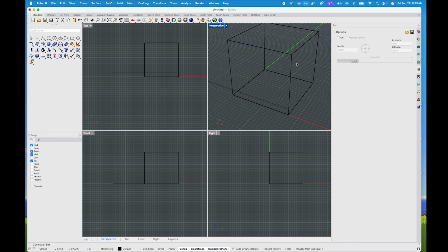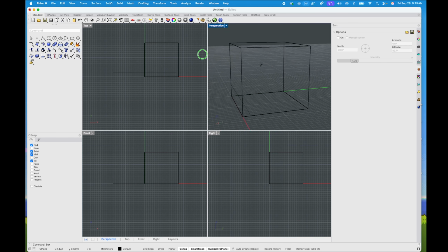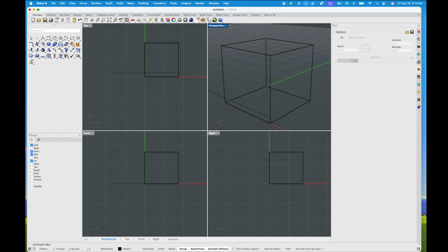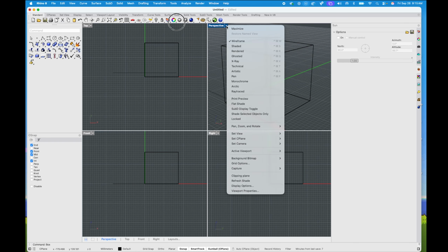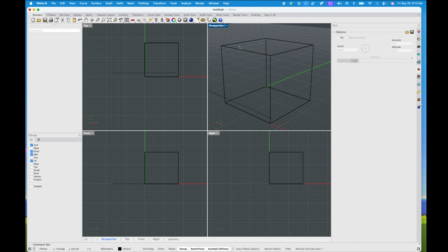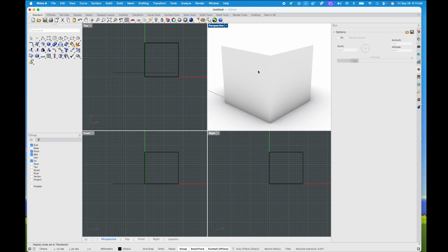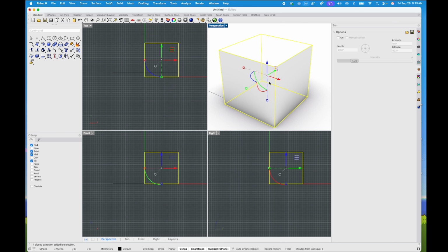Now, of course, by default, it's in kind of a 1980s video game wireframe mode. And that's definitely not the best way to look at a solid object. So one thing I can do to that viewport is click the down arrow and switch it to shaded. I can even instantly switch it to a rendered view and get a more realistic view of this object. I'm going to make a few of them today and show you some of the relatively simple steps in making these items.